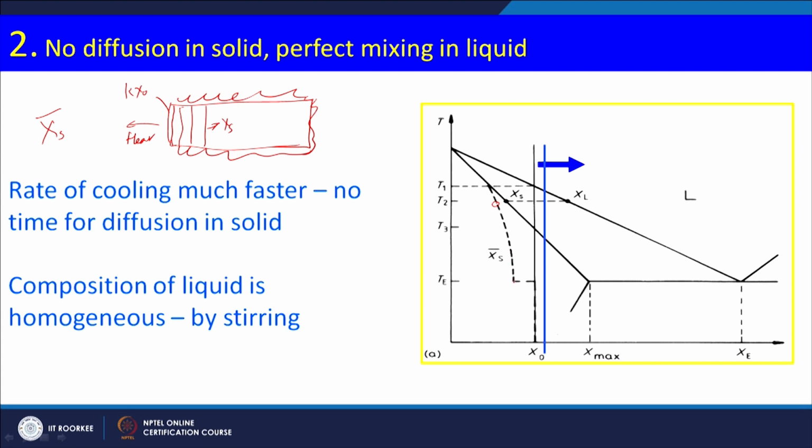The graph is coming like this, and where the eutectic reaction or isotherm of the eutectic temperature is there, at that point the remaining liquid, the solute content of remaining liquid which is increasing continuously, is reaching the eutectic composition. So, the remaining last part of the liquid, so my solid will keep on growing with a lower composition than what is given by that, and the last part of the liquid will transform with a eutectic composition.